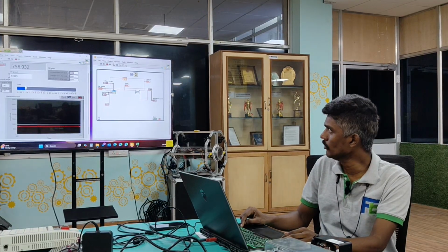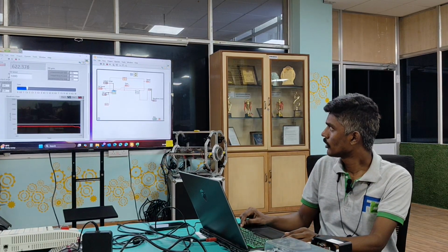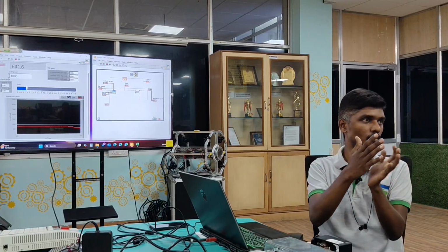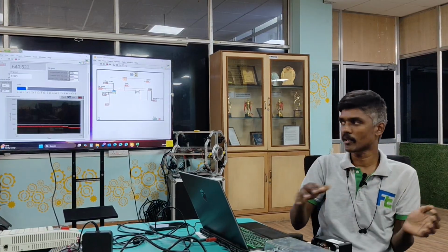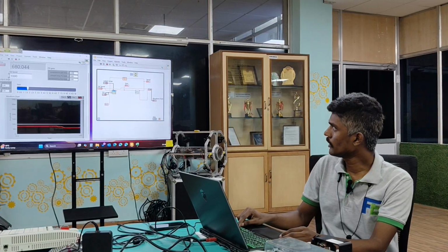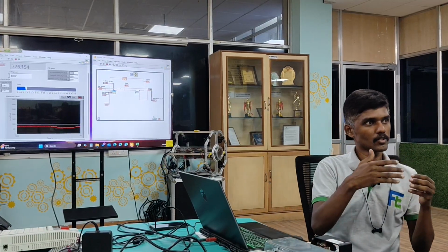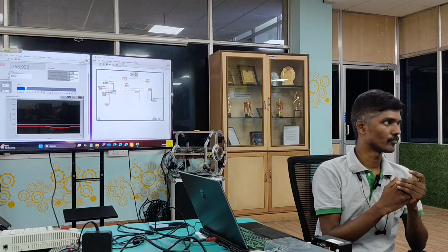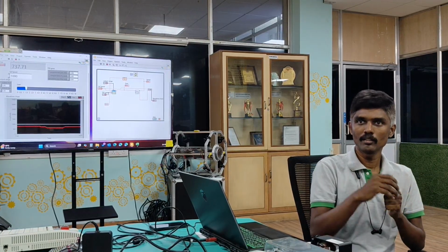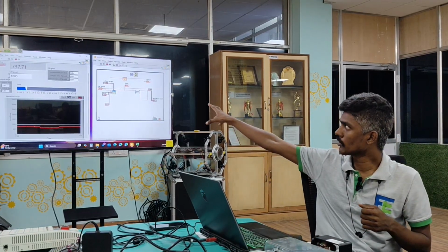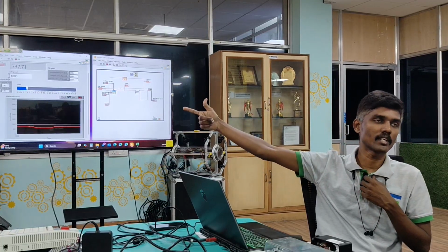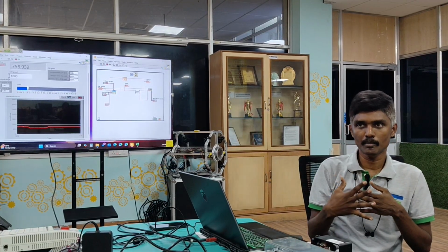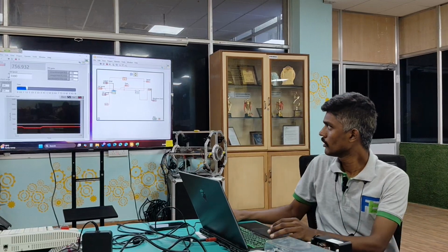If I reduce this value, your error band will increase. Like instead of 180 to 200 RPM, 300 RPM or 400 RPM. Make sure that initially you are getting 60 to 80% of your original value. Whenever you want to tune manually, before touching your integral as well as derivative gain, slowly increase your proportional gain value and get the constant error.